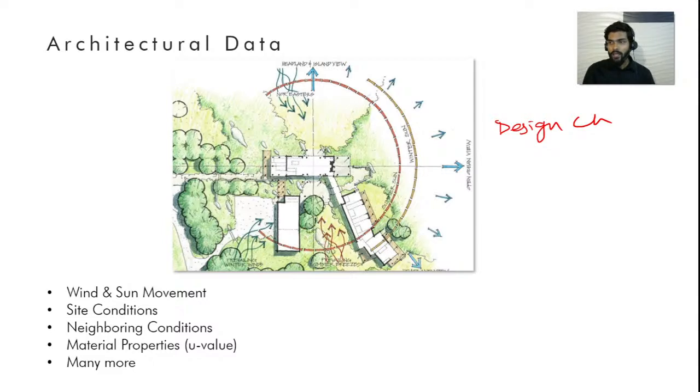Okay. So, whenever we are presented with a design challenge, be it a hypothetical exercise or a real live project design challenge or a problem, I could also say a design problem, what do we do? We collect data. Data like what is the bearing capacity of the soil of the site? What are the visibility angles? Where is north? What is the wind condition on the site? What is the rain condition on the site? What is the humidity level?